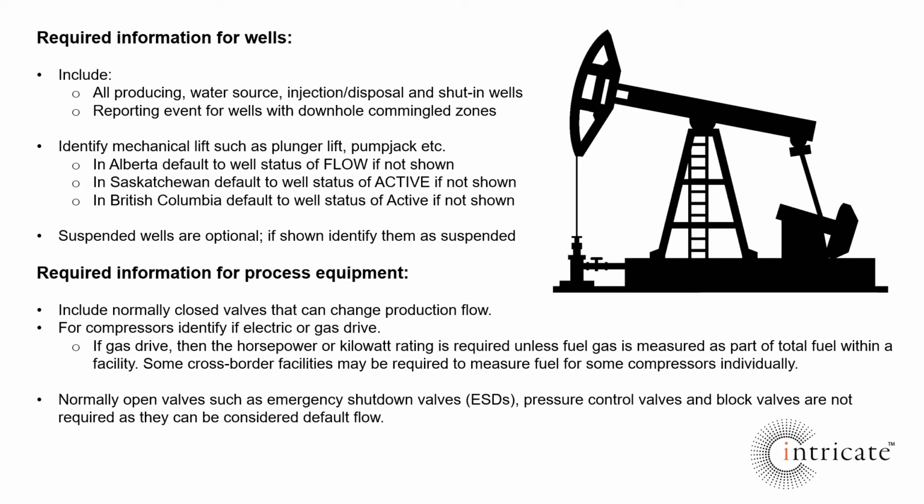Normally open valves such as emergency shutdown valves, pressure control valves, and block valves are not required as they can be considered default flow. Pressure safety valves are not required.